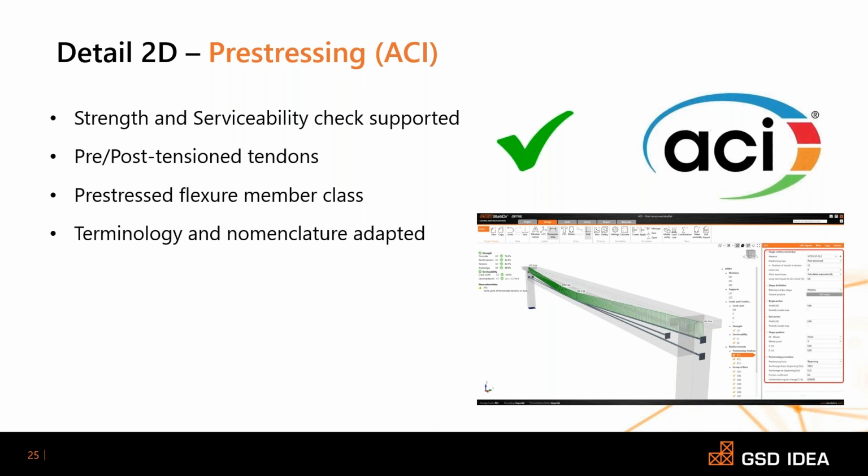Now designers can input both pre and post tension tendons. This improvement also has a database of pre-stressing steel, so you need not worry about the database. And the best part is that now you can also input the partially loaded area, and all required ACI standard checks, including the stress limitation and decompression check, would be definitely carried out.